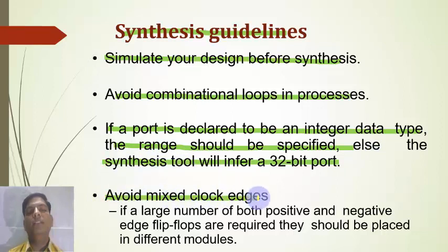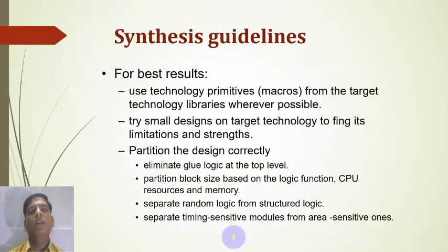Avoid mixing clock edges. If a large number of both positive and negative edge flip-flops are required, then they should be placed in different modules. So, synthesis guidelines: simulate your design before synthesis. Avoid combinational loops in a process. If a port is declared to be an integer data type, the range should be specified, else the synthesis tool will infer a 32-bit port. Avoid mixing of clock edges.